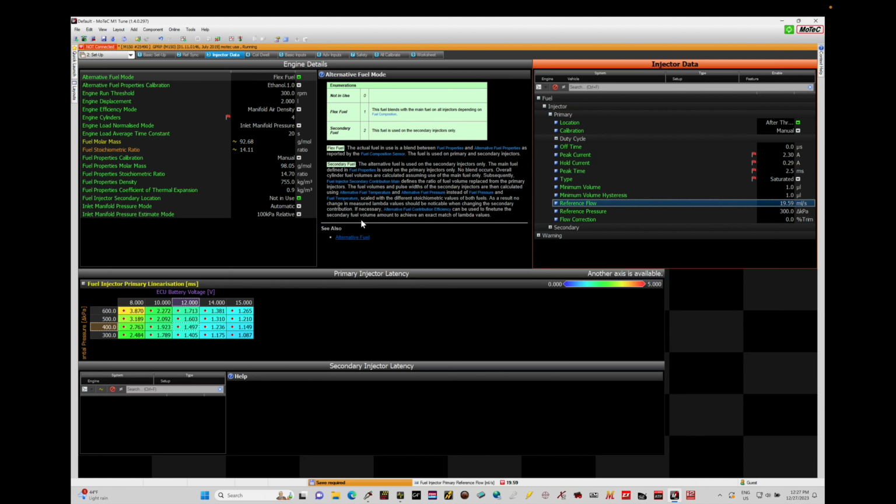So converting a fuel mass into an injector pulse width is going to be very specific in terms of knowing the injector flow rate. If we have a really small injector, it's going to take a relatively large injector pulse width to be able to open and close that injector to deliver the fuel that we're requesting, compared to a very large fuel injector.